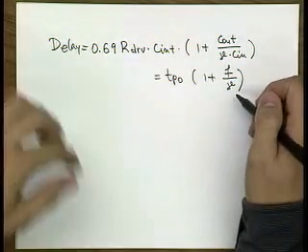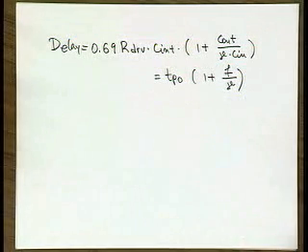Okay? So now, since you're really dealing with gate capacitance, because that relates to the sizing of your gate, you would rather work with the gate capacitance than the intrinsic capacitance. Intrinsic capacitance is good. It tells you what your propagation delay t_p0 is for an unloaded case, but that's a rather unrealistic case. It's just some time constant for a gate.